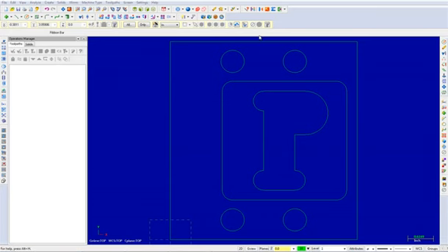We will now translate the entities. Translate Join transforms a copy of the selected entities to a new position in the graphics window and maintains the position of the original entities. Mastercam creates lines or arcs to connect the endpoints of the original entities to the endpoints of the transformed entities. Select the Xform Translate command as shown.